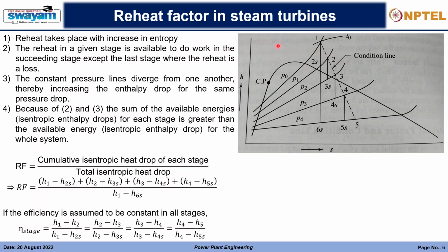In that, we are using different stages, going to the boiler, heating the steam, and then again coming to the turbine. That is completely different. This is due to the internal friction losses. It is getting some heat to the second stage or the next stages, but that is only beneficial to the first few stages, not to the last stage, because in the last stage whatever enthalpy is gained is actually going to the condenser, it is being lost.